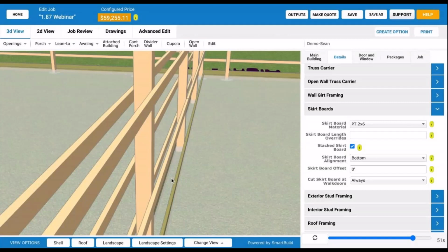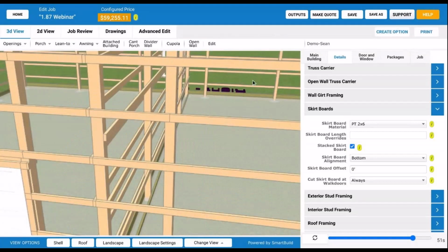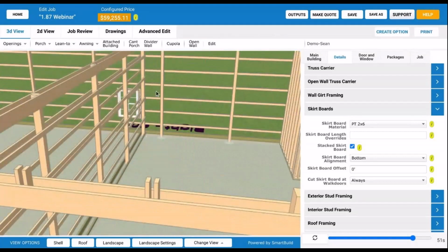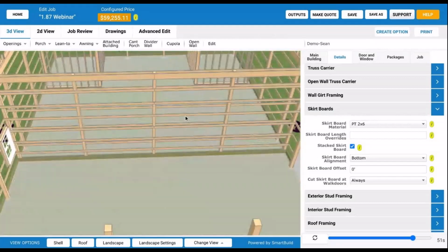Correct, the wainscot backer stiffens up that long span on the wainscot. It runs in between the posts here, kind of like a commercial girt. So it's something probably doable that would probably be quick. Yeah, it's good. It's definitely something we can do.